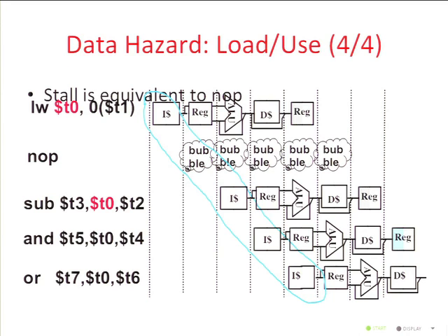Yeah? So you could just have a mux to choose between the register read and the forwarded value and put that into the ALU? Yeah, so you have to, remember, anywhere that there's a choice, so you'd either be getting something from the register or from the ALU, there's going to be a mux there, and there's going to have to be a signal that controls that mux. Absolutely.